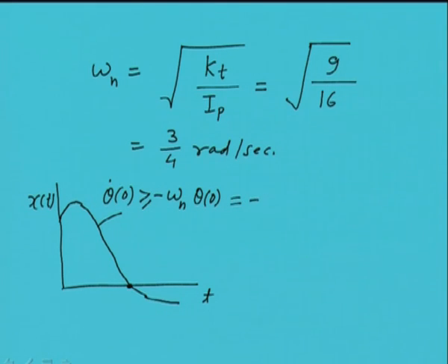Here we know the natural frequency, and we know that the maximum opening of the door is 60 degrees, so that is pi by 3. So this gives us pi by 4 radians per second as the angular velocity of the door if we give it at the initial maximum position of the door. It may just not hit the door. So this is the minimum. If we give more than this, then it will hit the frame, which is not desirable.